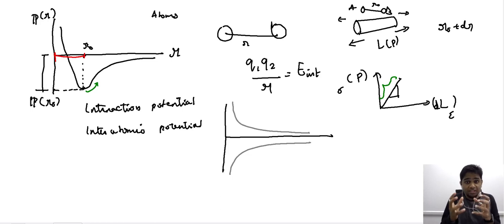This is one extrapolation that we can make from the atomistic perspective to what we observe in the macroscopic world. In the macroscopic world, within the elastic region, you impose a tensile load, you release it, and the system gets back to its original shape. The cylindrical sample that we have extends its longitudinal dimension once you impose the load, and gets back to its original shape once you release it.